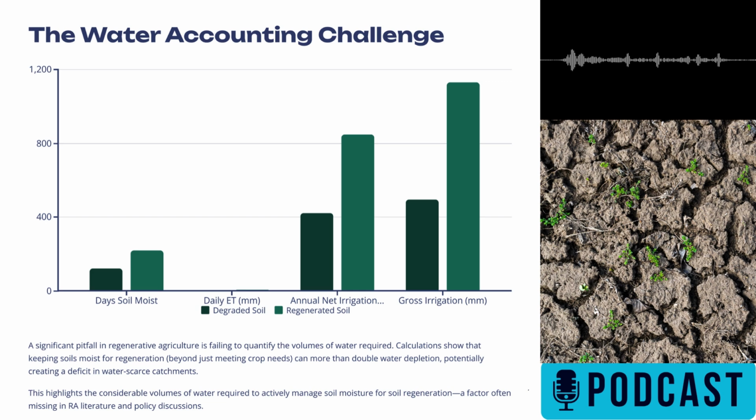Not quite. The water between FC and PWP is the total available moisture, TAM. Okay, TAM. RAM is the portion of that TAM that plants can access really easily without stress. It's the readily available part. The sweet spot. Exactly. Think of it this way. A sandy soil, or maybe a shallow soil, might have a low TAM overall, let's say 40 millimeters. Now, if a crop is using, say, 5 millimeters of water each day through evapotranspiration, that 40 millimeters runs out in about 8 days. Right. The plant starts feeling drought stress pretty quickly.